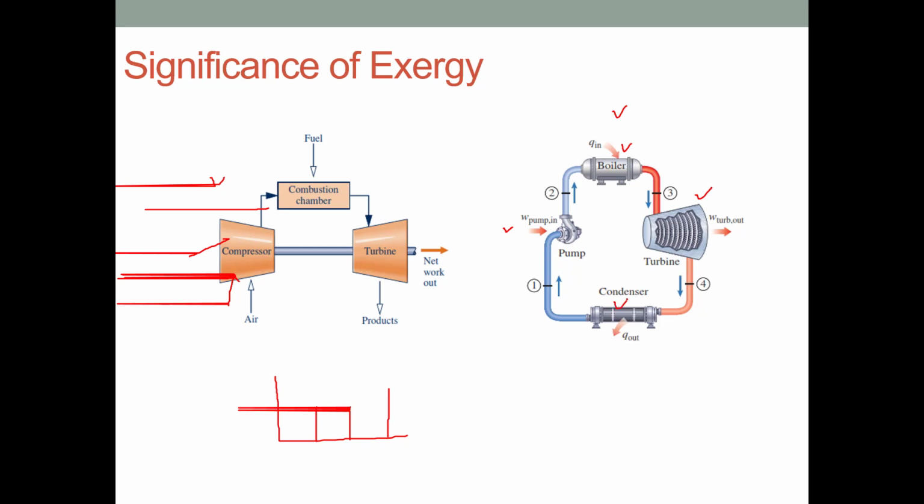For these four components, we'll draw a graph, one for the boiler, one for the steam turbine, one for the condenser, one for the pump. We'll focus on those components where the loss of exergy is very high, and then we'll try to dig out the reason why our useful work has been destroyed in these components.